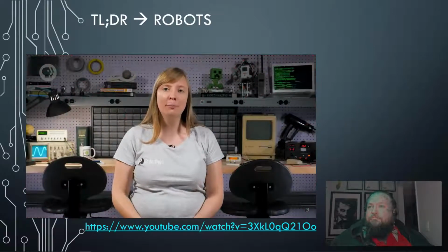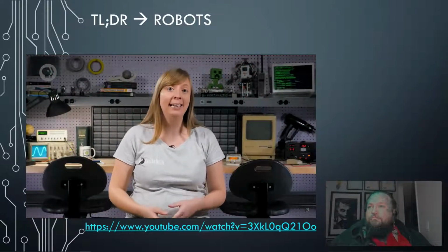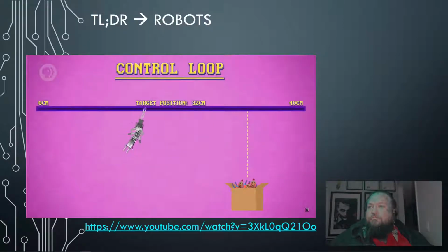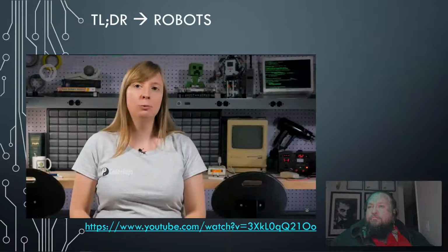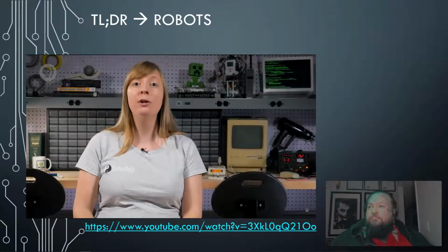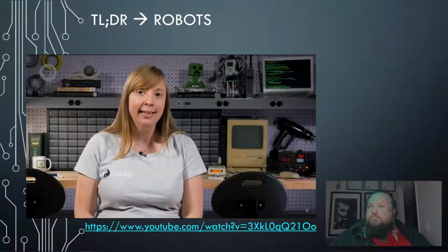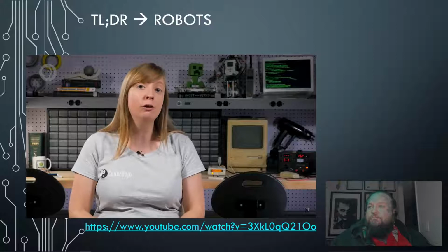In tightly controlled environments, simple control loops like this work okay, but in many real-world applications, things are a tad more complicated. Imagine that our gripper is really heavy, and even when the control loop says to stop, momentum causes the gripper to overshoot the desired position. That would cause the control loop to take over again, this time backing the gripper up. A badly tuned control loop might overshoot and overshoot and overshoot, and maybe even wobble forever. To make matters worse, in real-world settings there are typically external and variable forces acting on a robot, like friction, wind, and items of different weight. To handle this gracefully, more sophisticated control logic is needed.